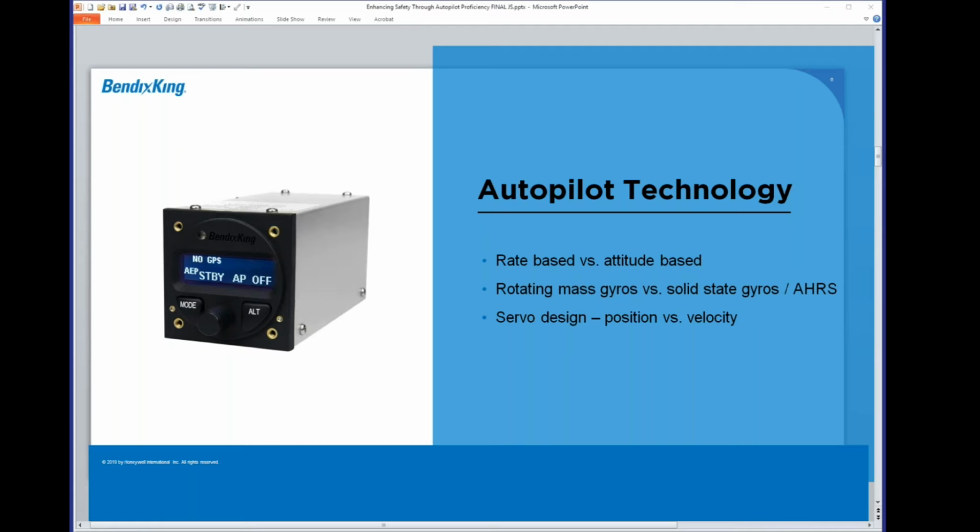In our velocity drive servo, we're commanding, again, a speed and a direction of that servo, and we actually let the airplane close that feedback loop for us. So it gives us a more simple servo, and it also removes points of failure. In some position servos, now not all, but in some, you have a feedback potentiometer that can fail in that servo, leading to an uncommanded drive of the servo in either direction at what would be equivalent to a hard over. So that's one of the reasons we remove that.